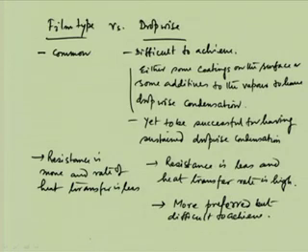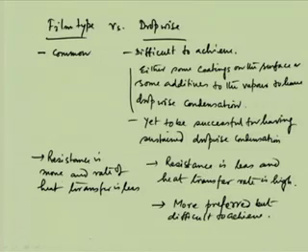So, now what we are telling, which is the very important thing, is that the resistance is more and the rate of heat transfer is less in case of film type condensation, whereas in dropwise condensation the resistance is less and the heat transfer rate is pretty high.